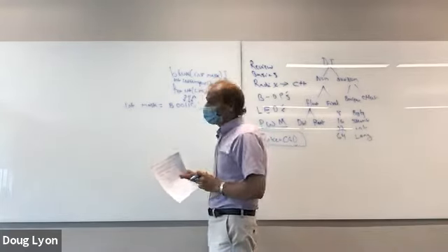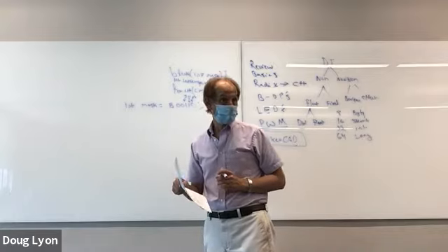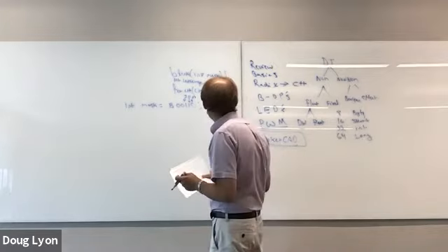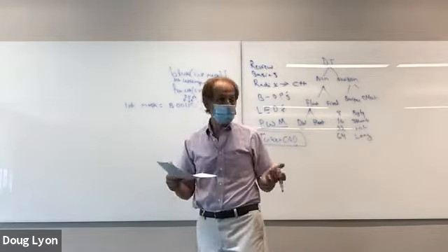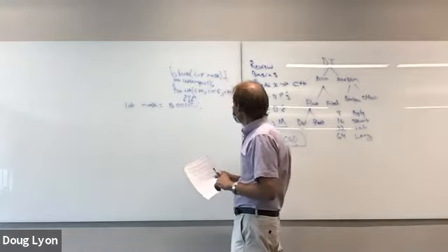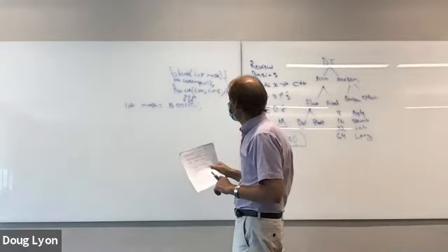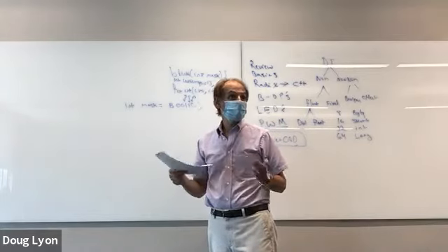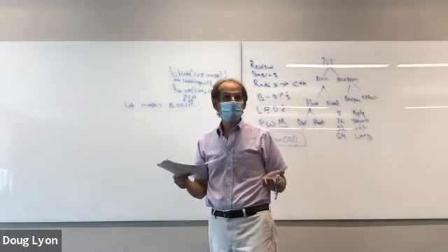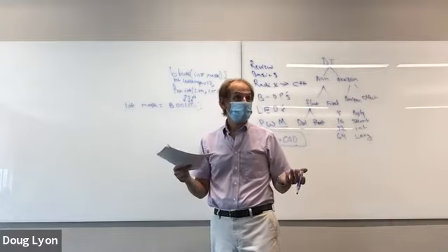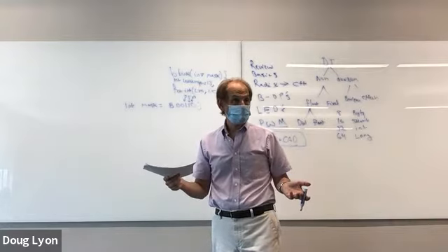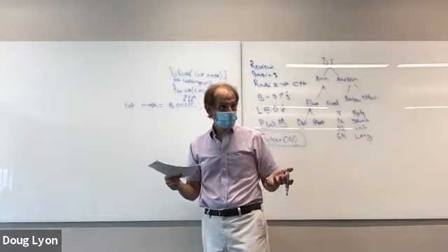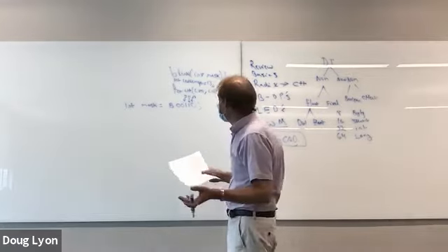So now here we are in this for loop, and we know we're going to examine, let's say, the least significant 5 bits, because we've got 5 LEDs. And so the first thing we want to do is identify the least significant bit in the mask. We want to know if it's 1 or 0. I know if it's even, it's a 0 for the least significant bit. If it's a 1, it's odd for the least significant bit. But I can identify and isolate the least significant bit with relative ease.